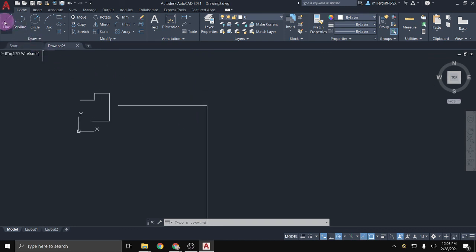One thing that hopefully you'll notice is when I'm in the line tool, as I'm drawing, I get that little green line that pops up. For me, it's at every 30 degrees. For you, it might be just popping up every 90 degrees. That's just depending on how you have that setting functioning and what you set the degree to. But what that is called is polar tracking. And so polar tracking is letting me know when I have my cursor pointed, in this case, at every 30 degrees, so that this way I can draw my lines nice and neat.